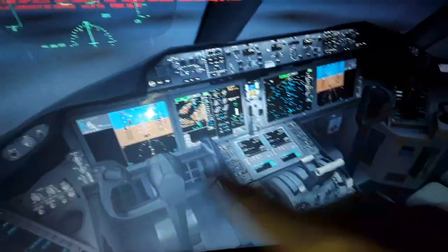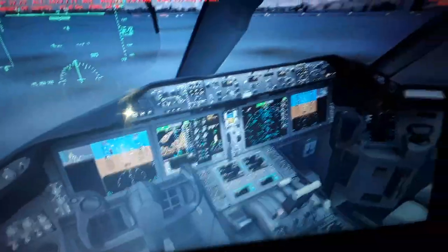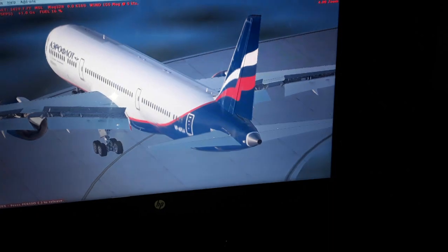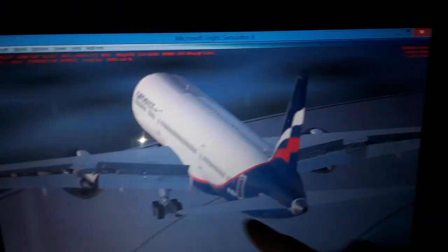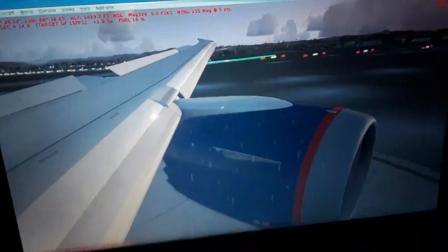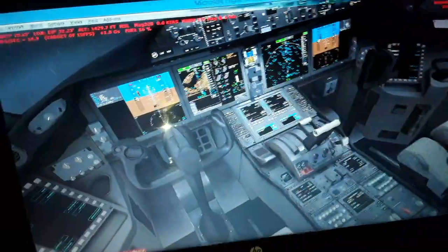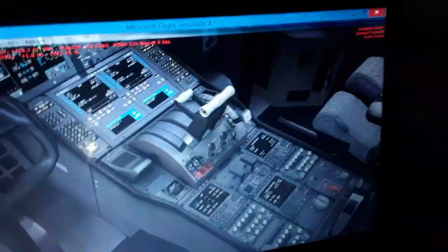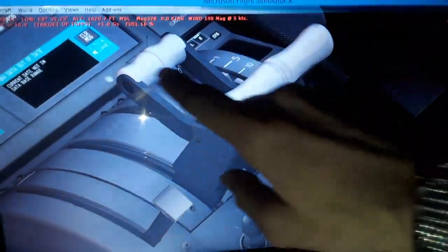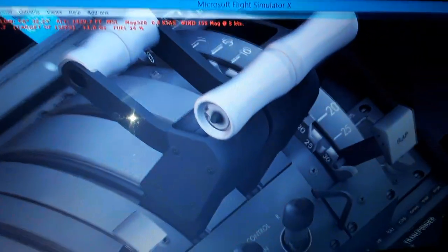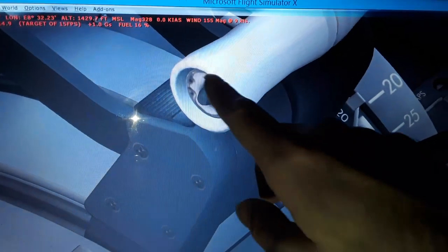We have the rudder pedals assigned. So you can see the elevator control, climb, descent, the rudder, aileron, spoilers. I will talk to you in a couple of minutes. Stabilizer trim also, the left and the right stabilizer, and elevators. So we have also here the thrust levers for the left and the right engine. As you can see, the thrust reverser, pull up this handle and reverse. You deploy the thrust reversers.